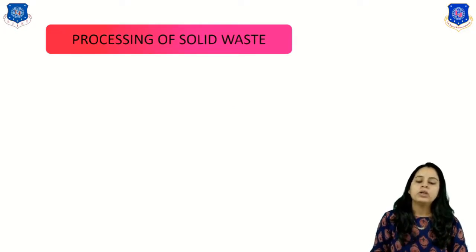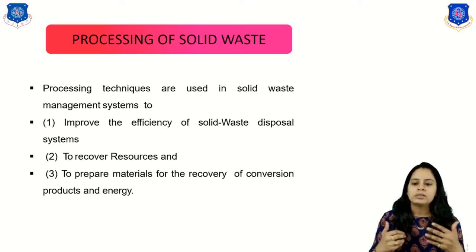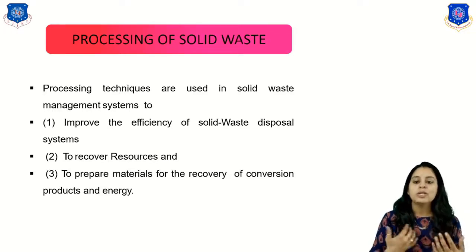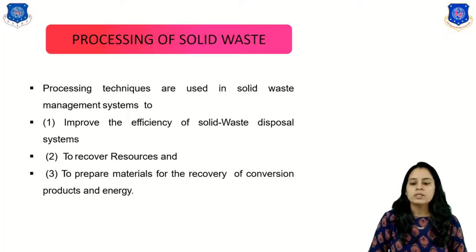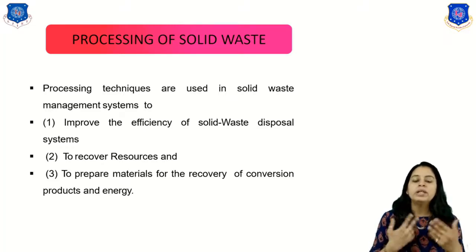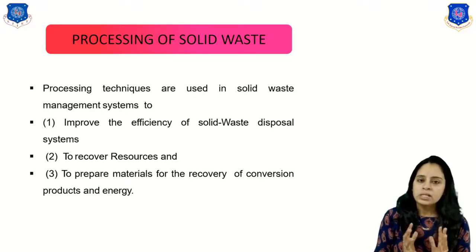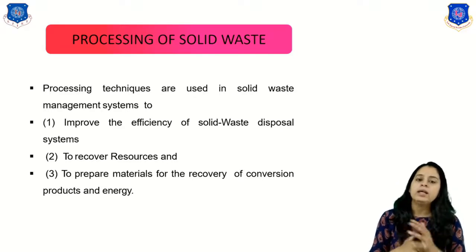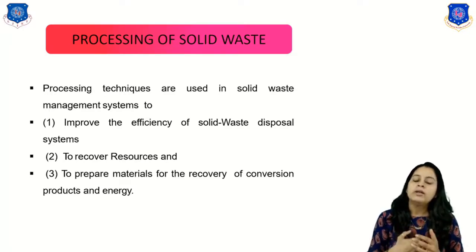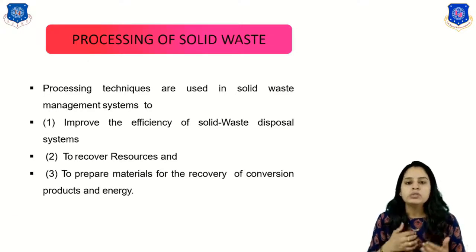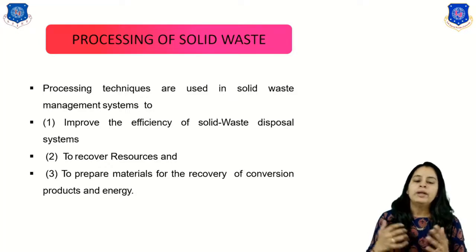Now the processing of the solid waste. This is the second step. Processing techniques are used in the solid waste management system for three reasons: the first is to improve the efficiency of the solid waste disposal system, the second is to recover resources, and the third is to prepare the material for the recovery of conservation products and energy. Processing means recycling and recovering the resources, so that we can reduce the volume or the quantity of the solid waste.